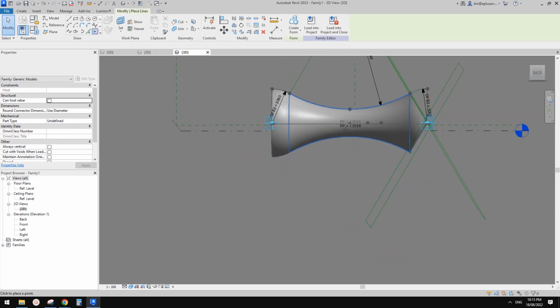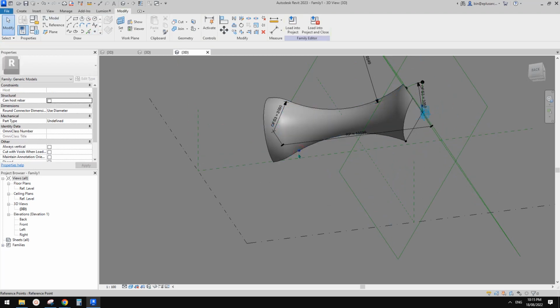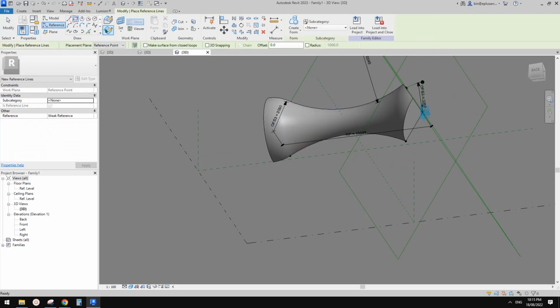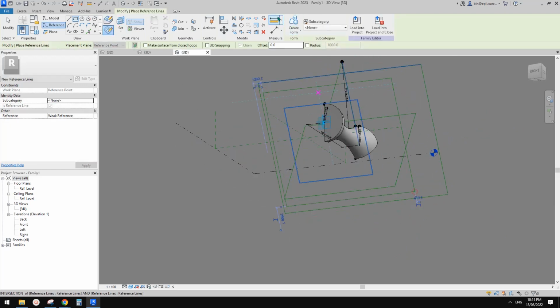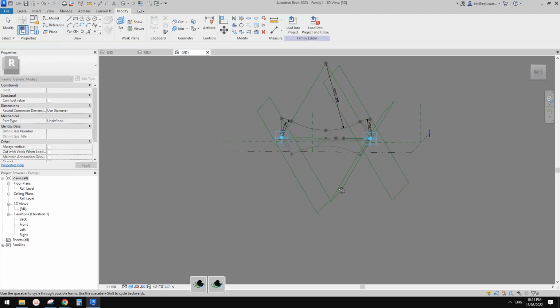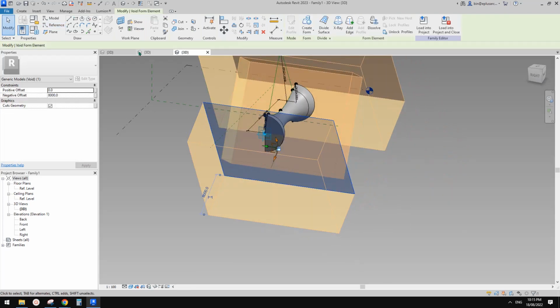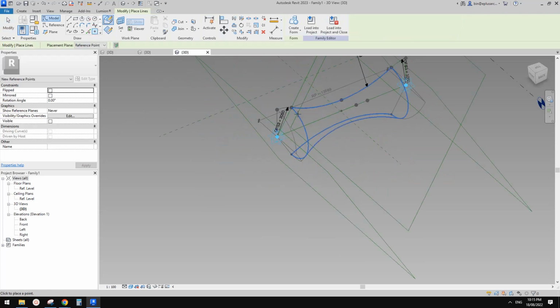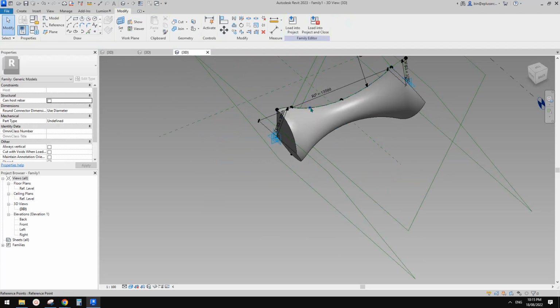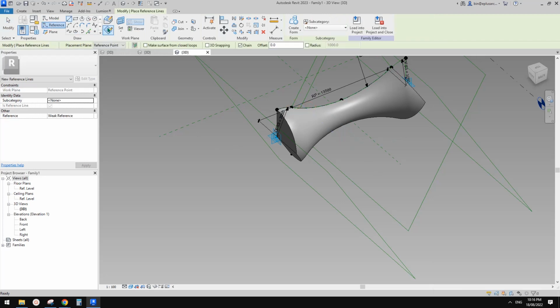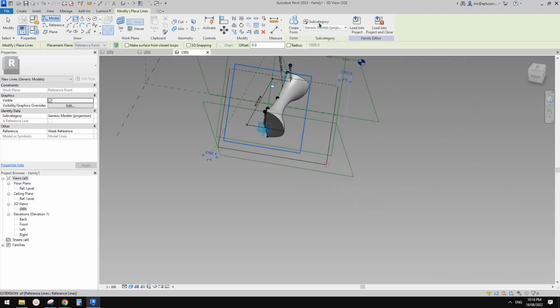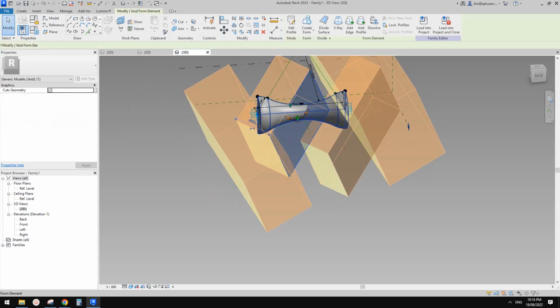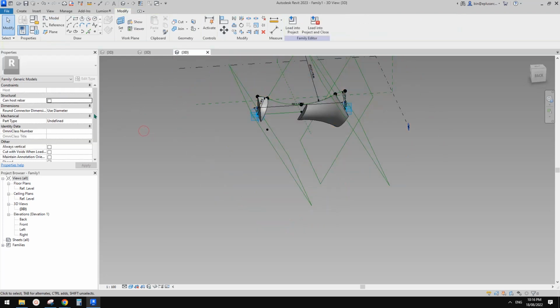Okay, so let's do another one. Drag it. Reference rectangle, set work plane, and just do a very big shape. A void, and the one on the left. Okay, good. Another one, draw on face, drag it to here, reference, draw on work plane, set work plane, rectangle, set work plane, and big enough. And the void, same, this one goes to the other side, create it first.